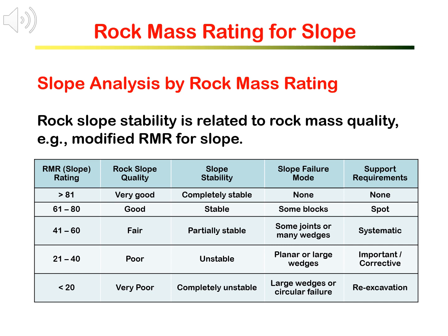Do you still remember rock mass rating, the RMR? It was taught in the rock mechanics course. RMR classifies the rock mass quality. We know that rock slope stability is related to rock mass quality. Slopes of good quality rock mass are more stable than that of poor rock mass. Therefore, rock mass quality can serve as a basis for slope stability assessment and the slope support design.